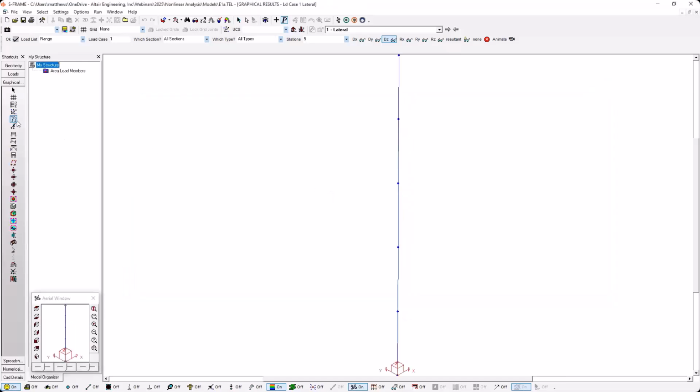And once again here, I just want to look at the deflections. That's really what I'm concerned about. And again, I don't see any Z displacement, which does make sense here. I also don't see any X displacement. So where we might notice a difference between P-delta and linear static analysis in this type of model is if we had some sort of compressive force on the column as well. But we don't have that in this scenario, so we're not necessarily going to get that difference.